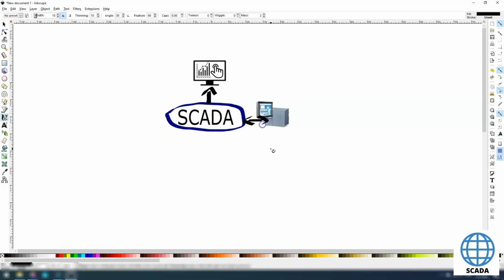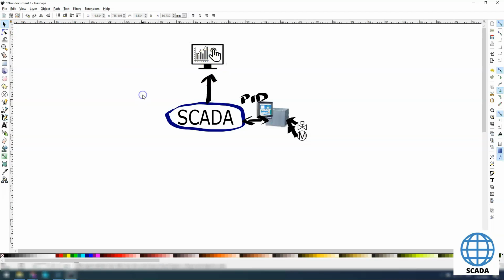The next one, we need the communication with PLC, RTU or PAC modules. In PLC we have the communication with valves, motors, pumps, transports, and other things. This PLC is the connector for SCADA, so SCADA can see the flow data from the sensor, from valves, from motors, and SCADA can send the data to PLC to make modification to system.